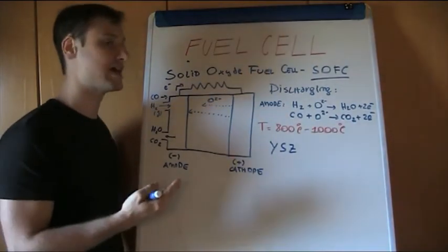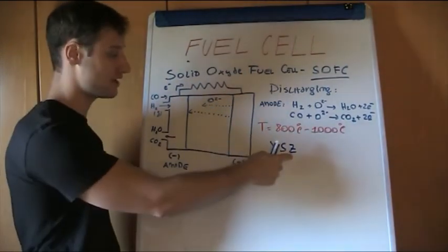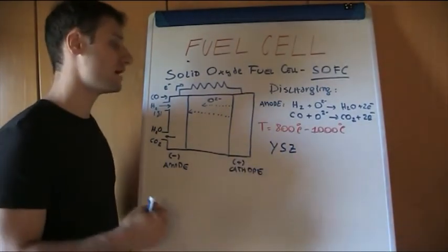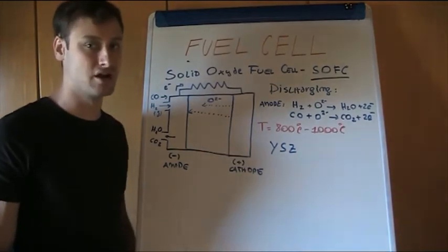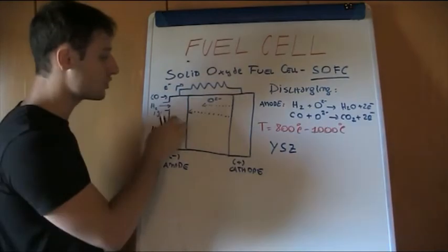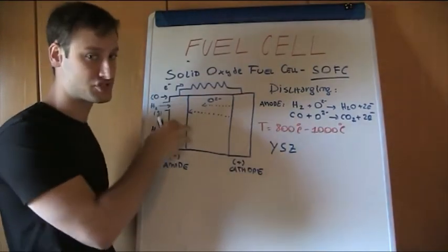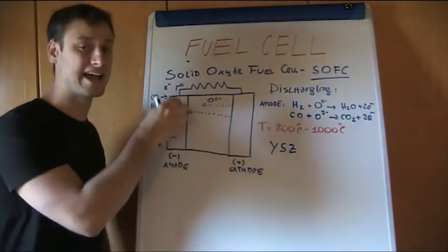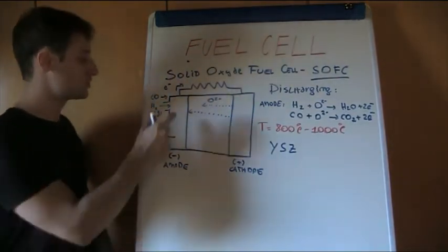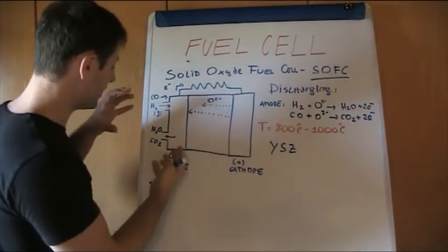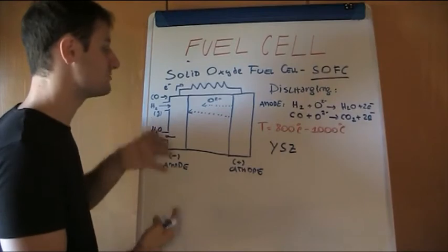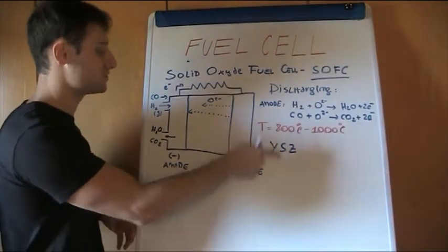So we are looking at a zirconium oxide, zirconia, in which yttrium oxide is used to stabilize a specific structure, allowing, together with nickel, a certain conductivity, a certain porous structure, and at the same time a catalyst place in which the oxidation reactions can occur. So the electrode is composed of nickel nanoparticles in a porous matrix of yttria stabilized zirconia.